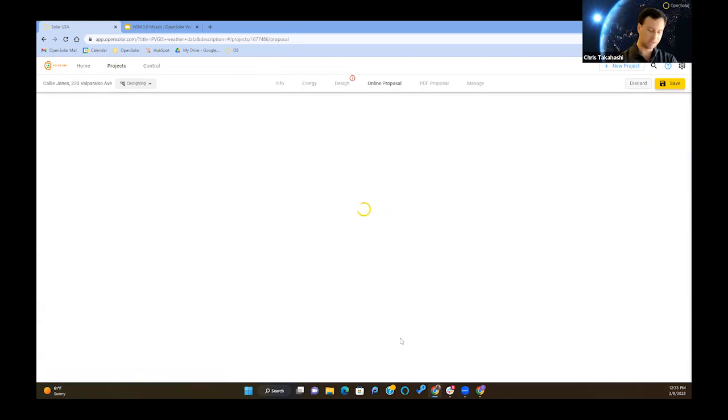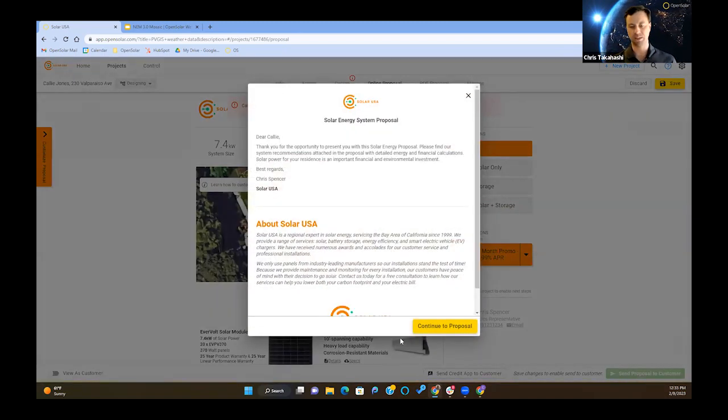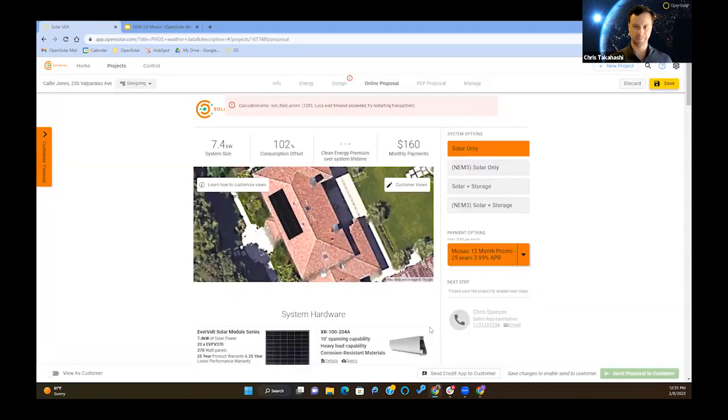And I didn't mention it right there, but we've got a bunch of different battery modeling schemes applied to projects, or just in your arsenal of what you can choose to use for battery modeling. The one I've used here is called a minimized time of use. So it's really making sure that the battery is going to charge during peak production and discharge during those peak power rates in the evening. So really just cut down on how much you actually are pulling from the utility, minimize that exposure to the grid, and maximize your savings in the process.